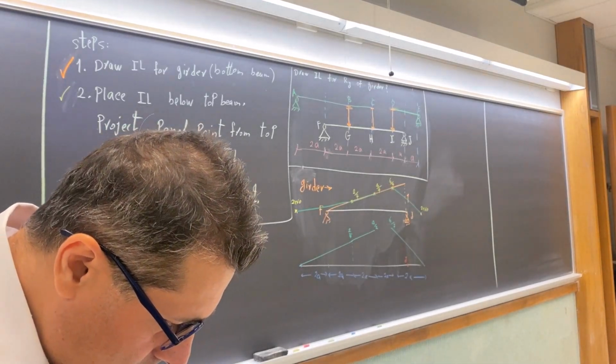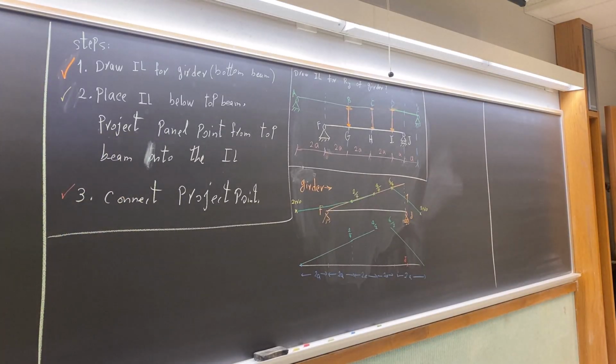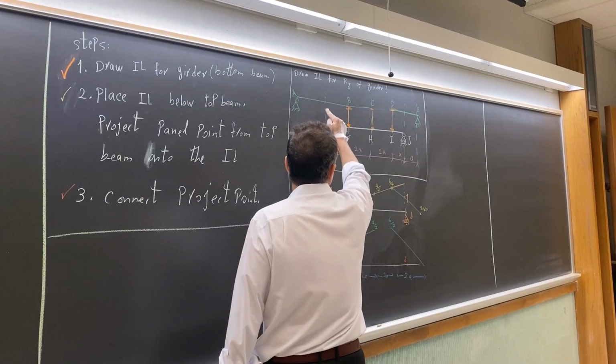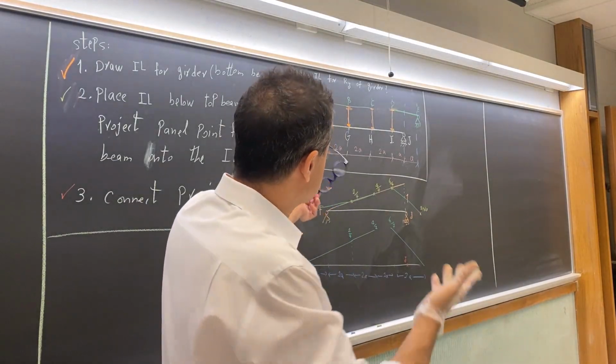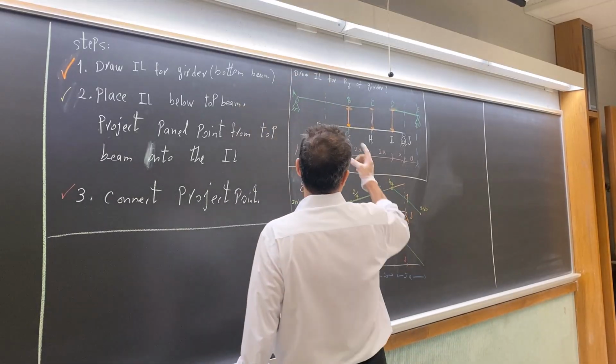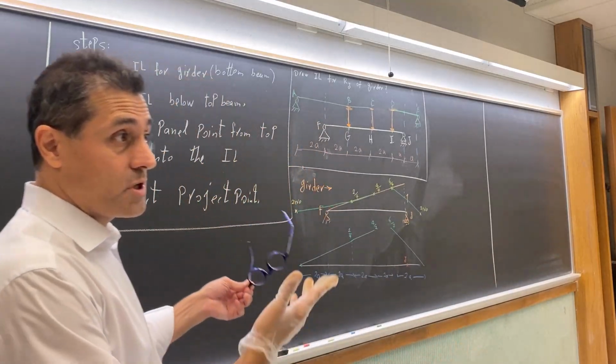Another thing is that, do we have a floor beam at point F? We don't have, because the question says so. Be careful about this. Maybe another question will place an I shape in here, a panel point. So be careful about these details.